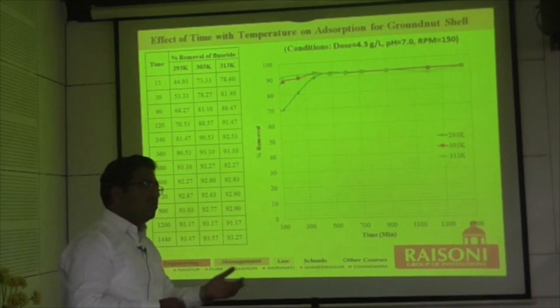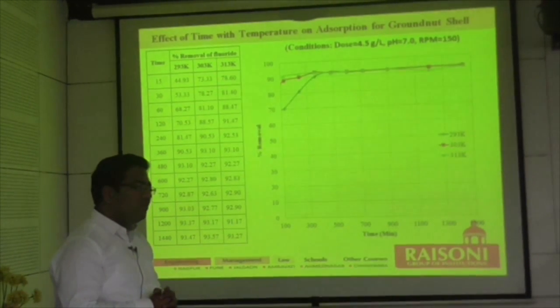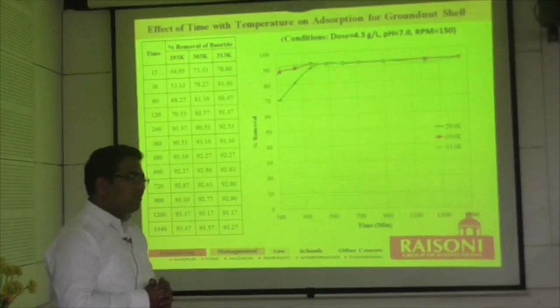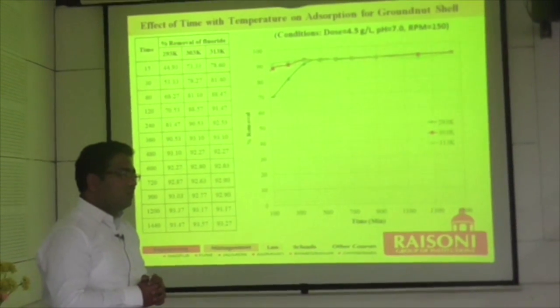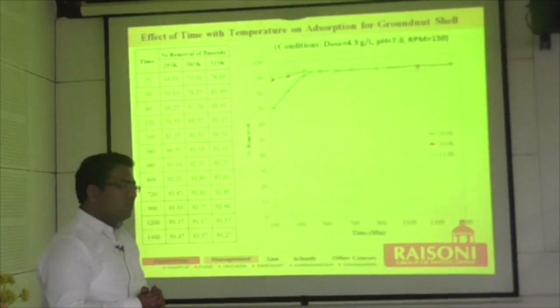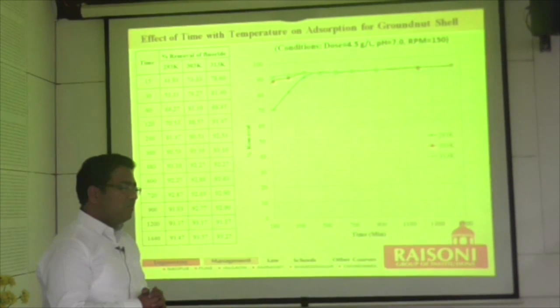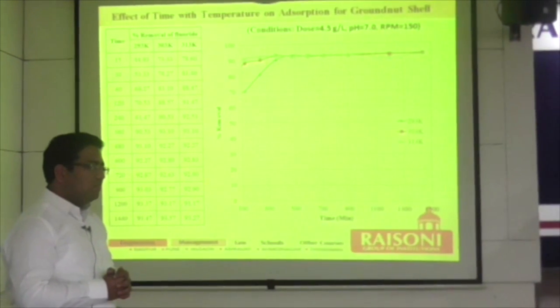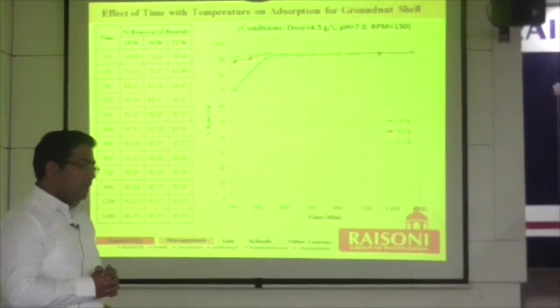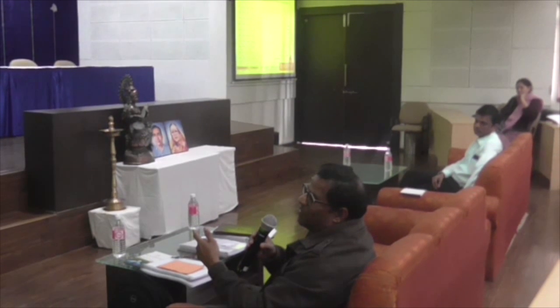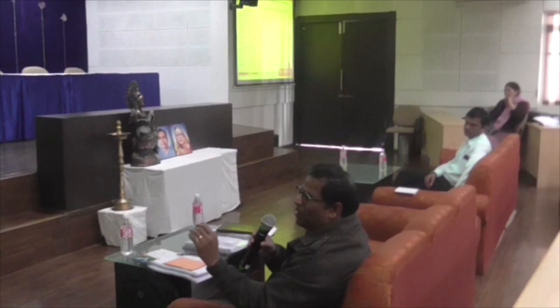I have a very serious problem here. I am really worried that you lost a lot of important information in the beginning. See, adsorption depends upon the concentration gradient. So the initial few minutes were actually very, very important. I really do not know what is the fun in taking it for 1,300 minutes and 1,500 minutes. I would have appreciated it if you had taken more values in the beginning.